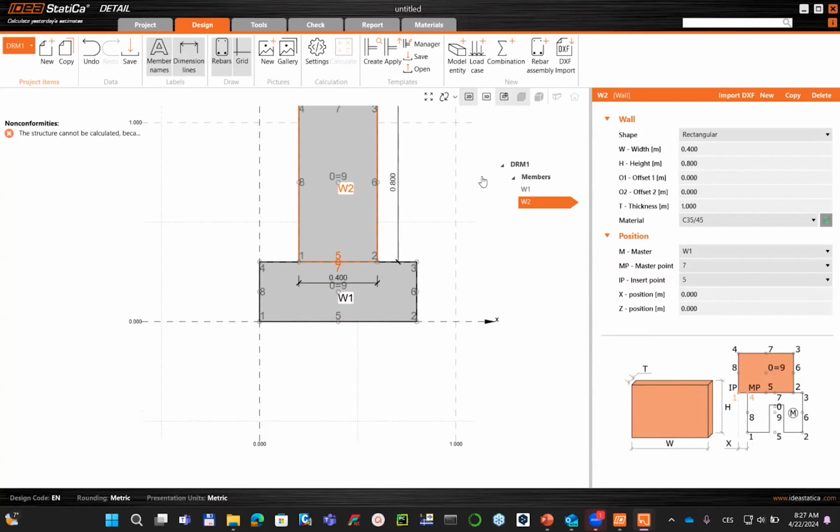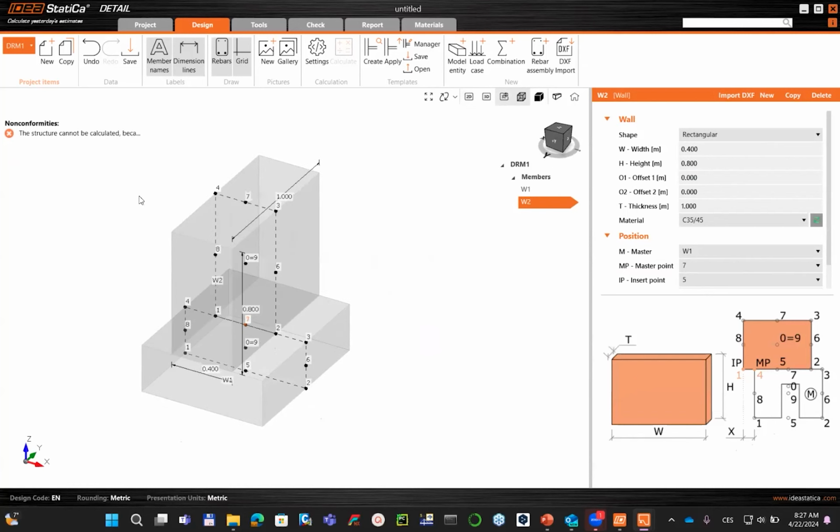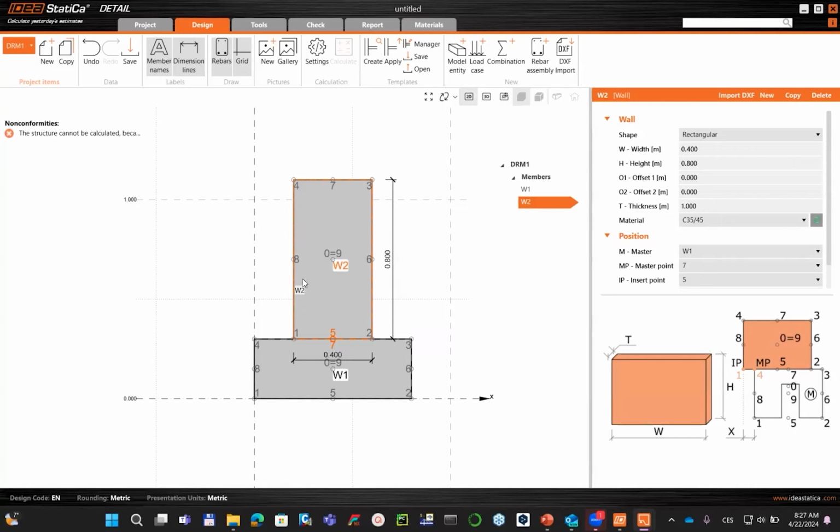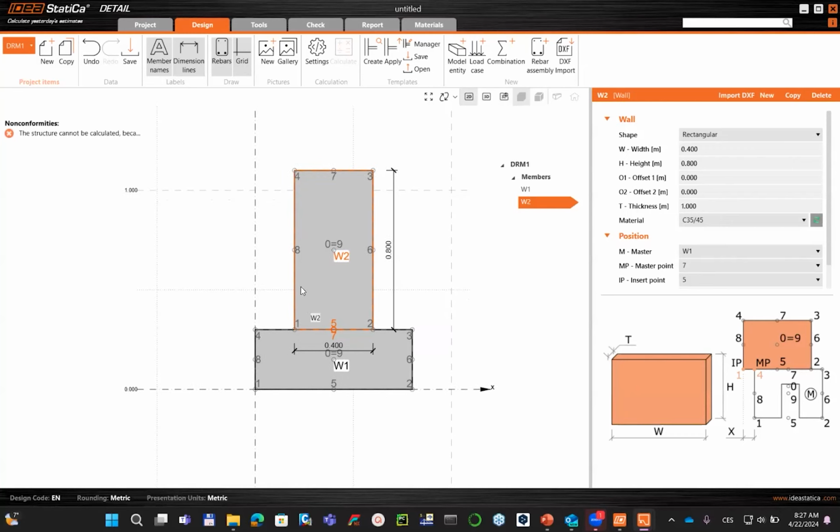So right now, if you check the geometry, I have created some cutout from the beam structure to assemble and code check the discontinuity regions that looks like this. Right now, what about the boundary condition? Because you can see the software is informing you that the structure is statically overdeterminate, so you need to put the boundary conditions for the analysis, because without boundary conditions, it's like a rigid body moving and you don't get any results.